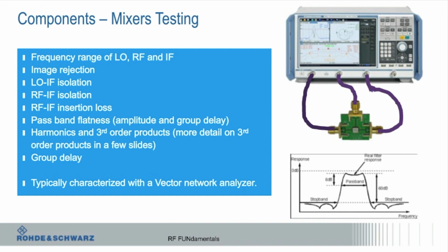So when you figure out what frequencies to use, you need to be really mindful of what frequencies you're picking, particularly for the LO, because that's usually the one you get to pick. Usually the RF is defined by the standard. If I'm doing cellular, the standard says I'm at 700 meg, an LTE phone. My A to D is at 70 megahertz. So I want to go from 700 to 70. Can I do an RF minus LO? Should I do something else? When you pick the LO frequency in particular, you want to know all the extra junk that gets through, whether it's going to be a problem, and whether I can filter it out, because you're going to have a filter in here somewhere.